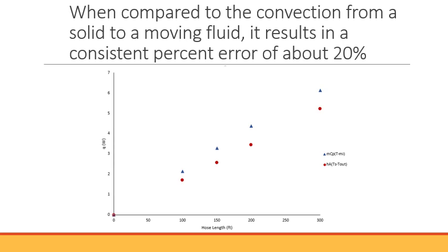First, the temperature of the surface where the water was in contact with the hose could not be measured, as the hose is an insulated hose. Thus, I assume that the change in temperature, delta T, was the same change between the mean in and mean out temperatures used for internal convection. I neglected any other modes of heat transfer and also any convection that might have taken place from the water to the insulated lining of the hose.